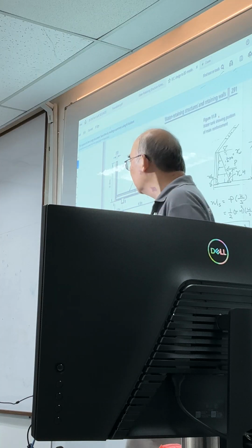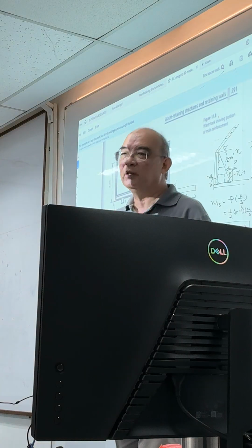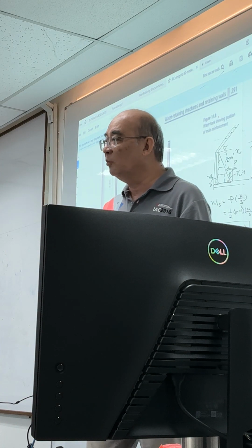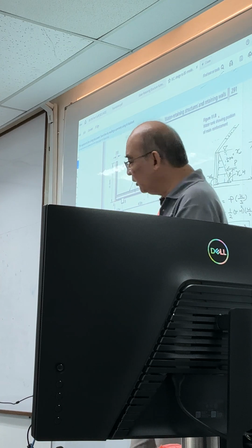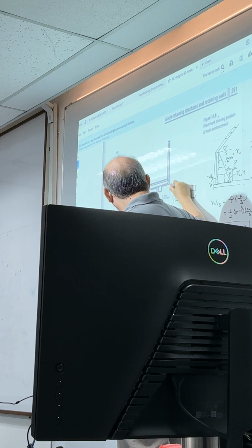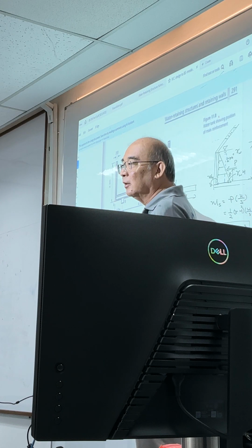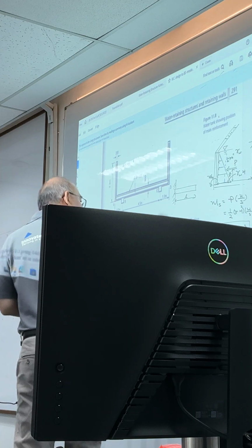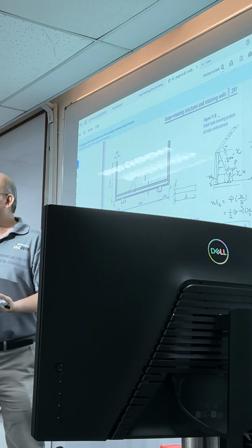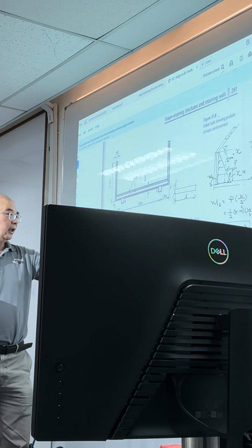I just take the clear span mainly because I started my career in the US, so we all design based on the clear span. Nobody questions. And the other reason is because when this thing is going to fail, it's going to fail here, not fail inside. So we are looking at the moment here. Anyhow, when we respect the British code, that's why I point this out. But in my test, you can ignore this stuff.